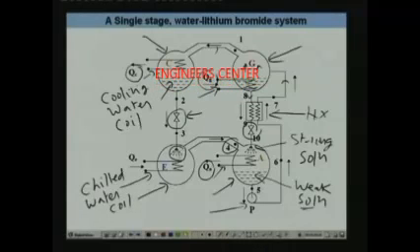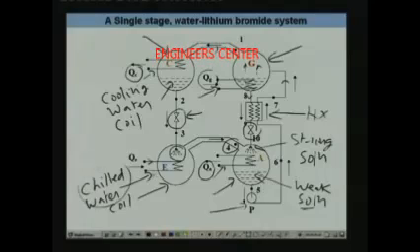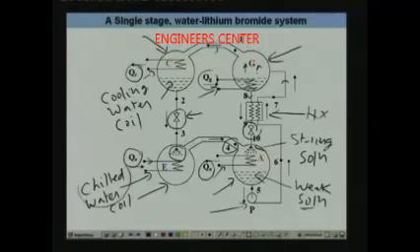As a result of it, since evaporation is endothermic, the water that is entering into this gets cooled. So ultimately what you get out of this is cold water. That is nothing but your refrigeration effect QE. And during this process liquid becomes vapor, and this vapor goes to the absorber,